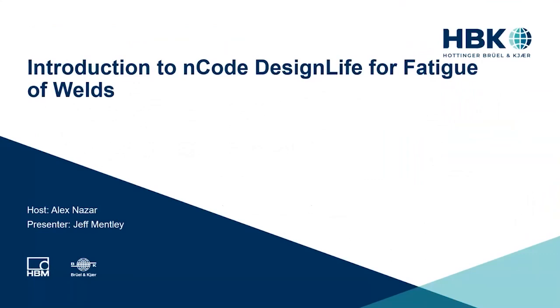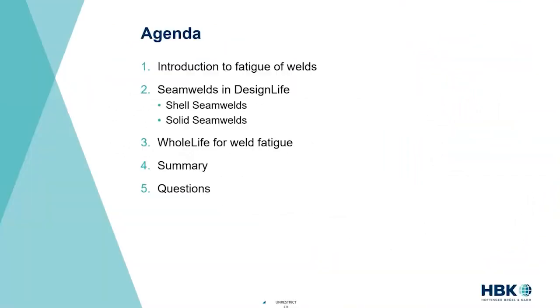With that, let's get started into the fatigue of welds. Again, we'll start with just a real brief introduction to categorize the challenges and techniques for looking at welds. I'm then going to talk primarily about seam welds today in DesignLife, both in terms of shell modeling and solid modeling, and the common areas as well as the differences. Again, I will talk about WholeLife, and then after the summary, we'll open up for questions.